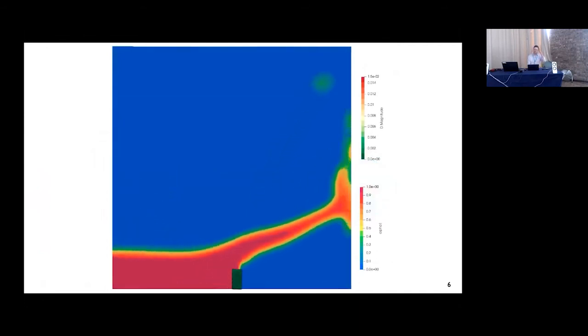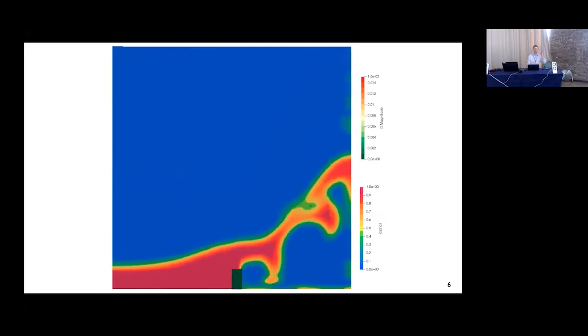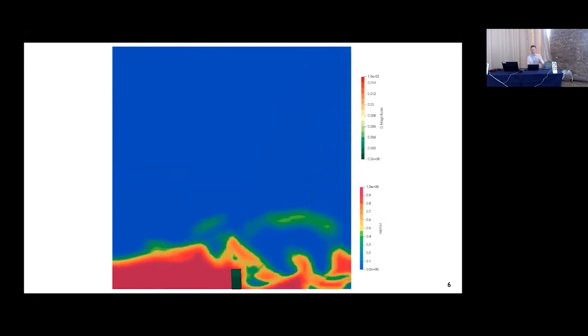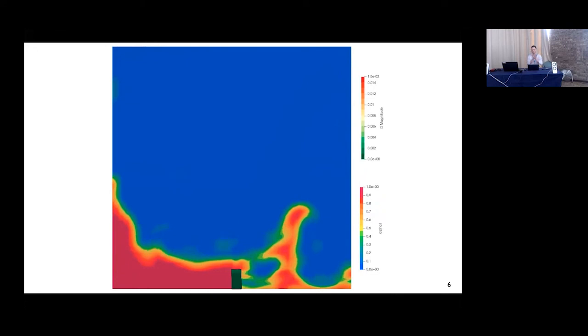So this is just dam break. It's just the standard interFoam dam break, except we just make the dam flexible, and then we run it. So we have a little elastic, rubber dam, so the fluid hits it and it bounces around. So this is one of the tutorials in Solids4Foam that you can try. Solids4Foam is not the only way to do FSI in OpenFOAM. There are a variety of different ways with different relative merits.